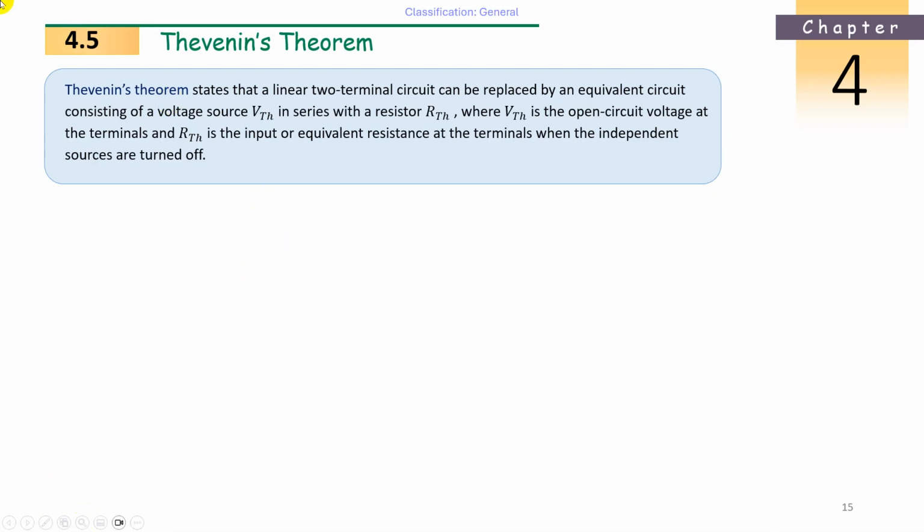Let us take we have 100 resistances, many voltage sources, current sources, dependent sources in one circuit. Now I am just simplifying the circuit and making it as one voltage source and one resistor. That's it. Means all will be simplified into two parts, that is two elements.